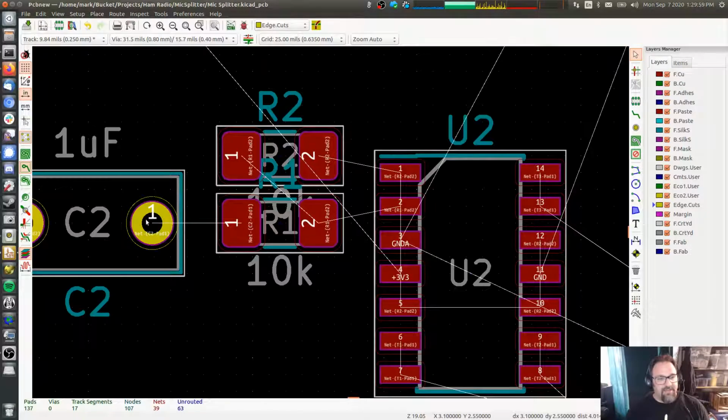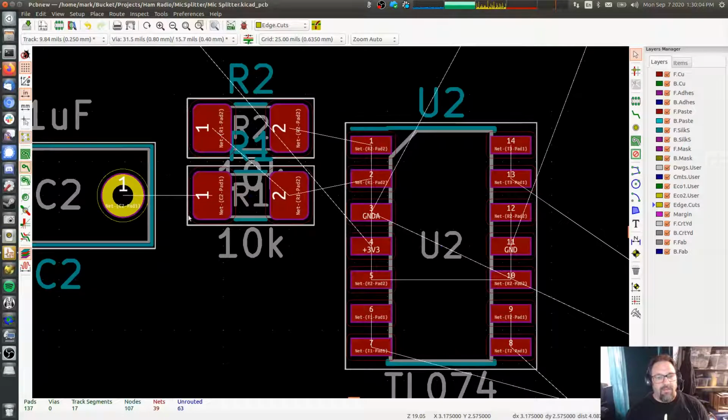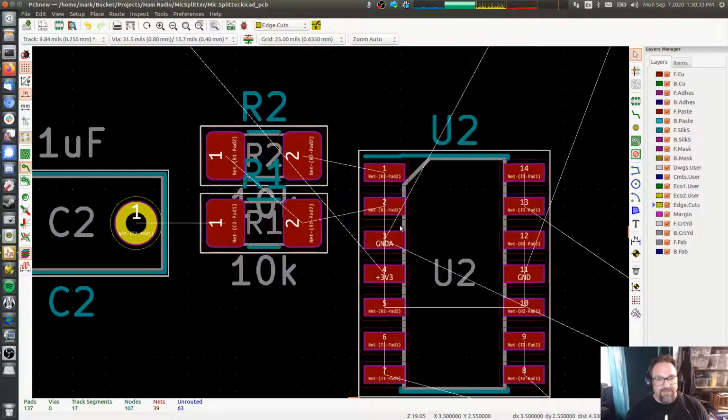So what I'm looking at is, the signal comes in from the connectors here, DC blocking cap, and then this is the input resistor to the input of the op amp, and then the output of the op amp is on pin 1, and that goes through the feedback resistor into the negative input, and then the positive input is here. This is our analog ground reference, right? Yeah, so that's the only pin that needs ground A. Okay, we can do this.